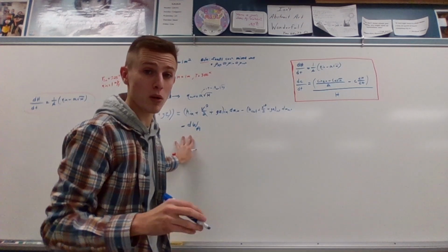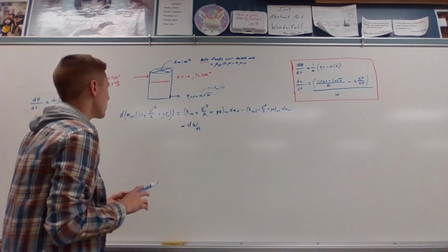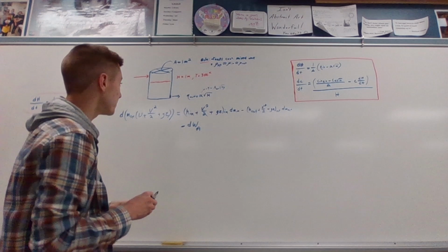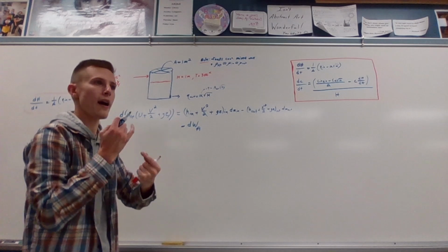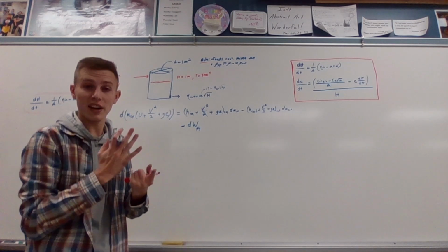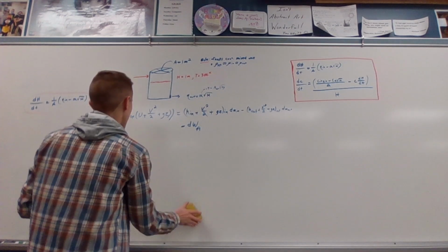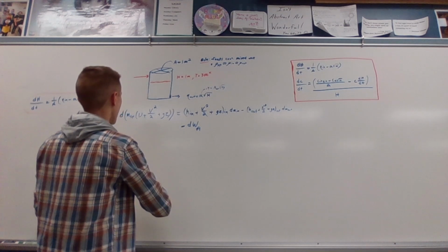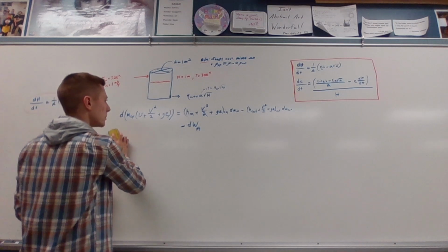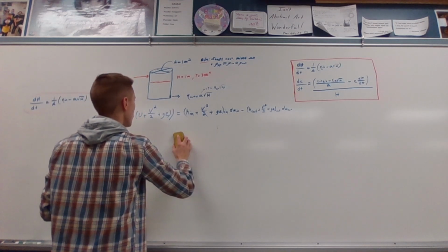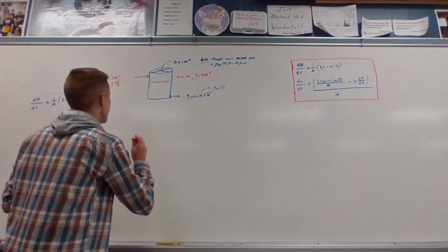Now for this particular equation, we are going to want to take out and simplify a few things. We're going to ignore a few terms which we would usually keep in here. We are going to ignore our non-flow work. We're going to ignore our kinetic energy and potential energy terms. So it's going to simplify to a much more manageable problem. Let's go ahead and do that. I'll erase this and write down the simplified version of it.